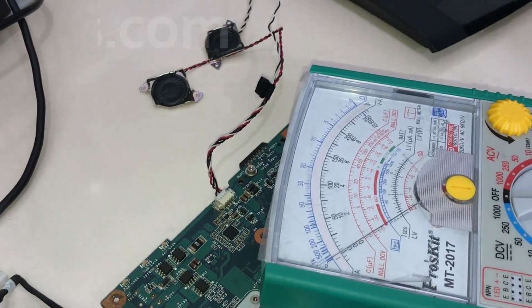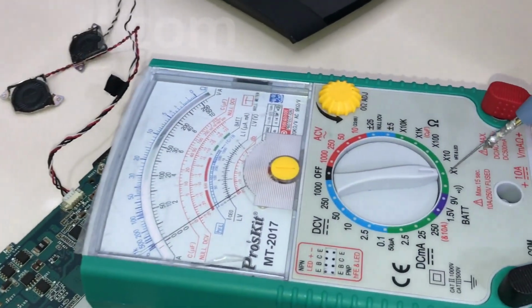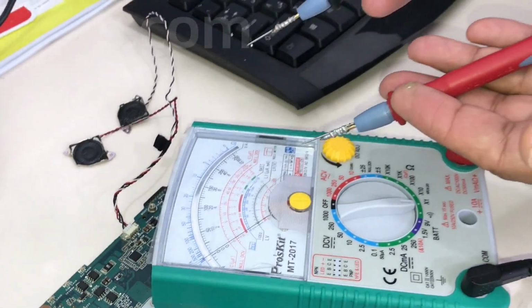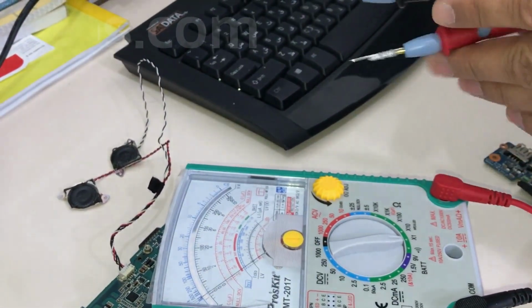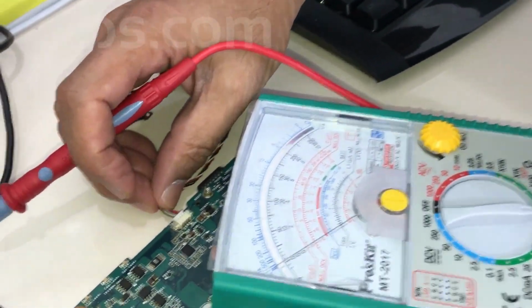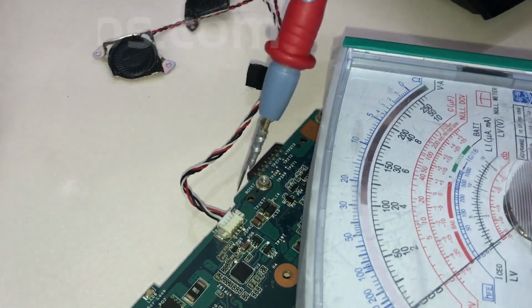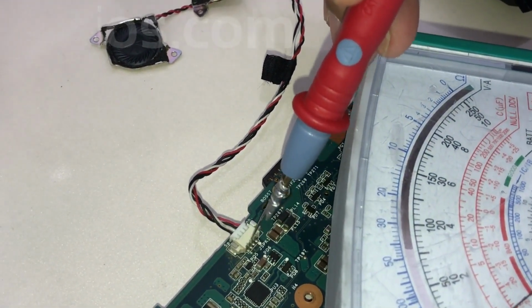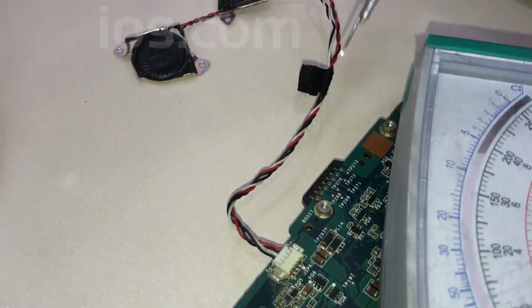With an analog ohm meter, in range R*1, there is no need to set 0. Probes don't matter either. There are 2 speakers, which can be seen on the connector. You don't even need to remove the speaker from the connector. You can also test the connector by placing the probes under the connector.